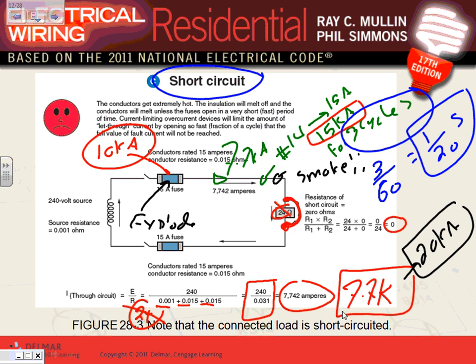So if anybody asks you what is the worst scenario for a short circuit, three-phase. When you take phase A, phase B, phase C, now the troublemakers, Oladipo, not Nick, grab phase A and phase B and put them in a wire knot and tie them together and turn the switch on. That's the worst scenario. If it's single phase, like this system, the worst scenario is take hot 1 and hot 2, tie them together with a wire knot, and turn the switch on.